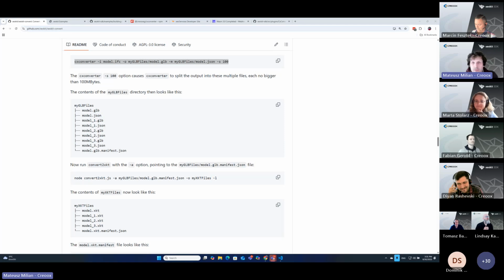Fabian here. So typically, for the user of xeokit, we recommend a standard pipeline, which contains two steps. One is this conversion from IFC file to GLB, and of course the metadata, so all this semantic information about the models, like properties of the door, whatever. There can be very, very different information stored in the meta model.